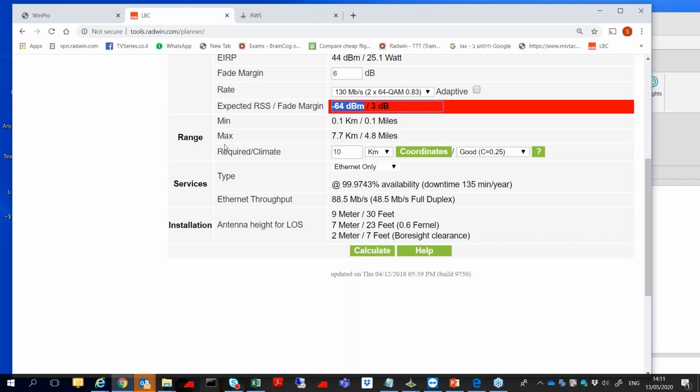The distance is a condition that you need to answer with a proper antenna gain and a proper TX power, and of course, you need to calculate which antenna gain you need to provide according to the link budget calculator and the modulation that you want to achieve.